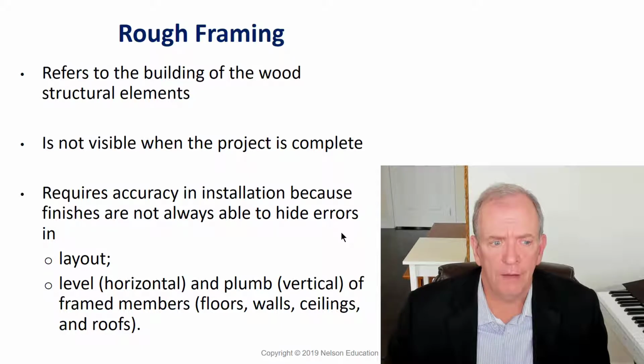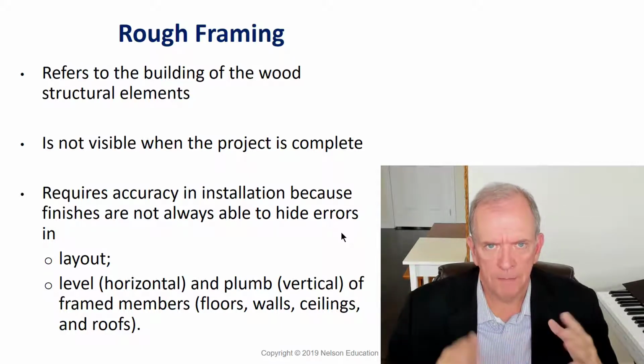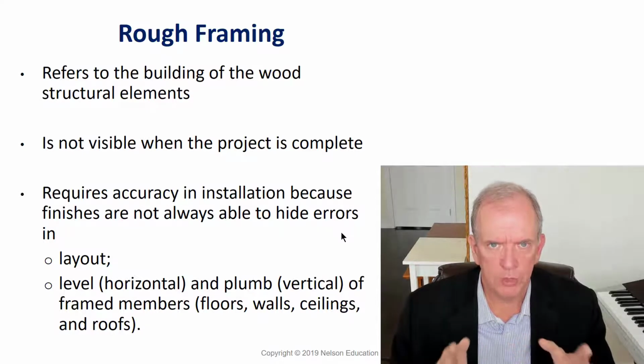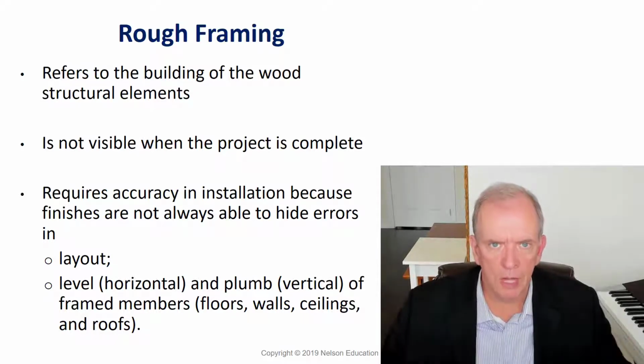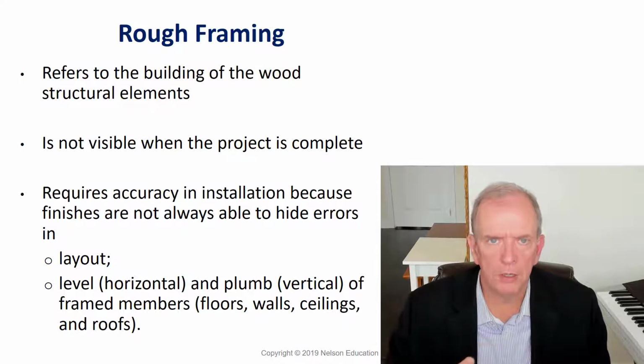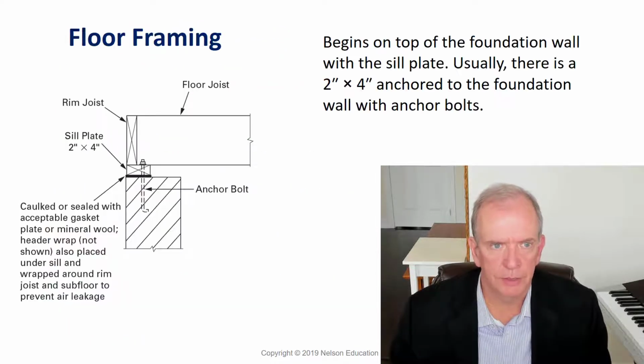So you have to be very, in my mind, fussy about the layout and ensure that things are square, plumb, and level within minor tolerances. What's a minor tolerance? It's okay, 1/4 of an inch here or there. Depends on how long I'm talking about, but very minor tolerances. And I've seen some buildings that are new buildings that are quite unacceptable that way. It just makes the whole thing all the way through a struggle for all the trades.